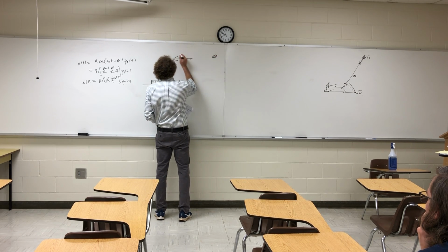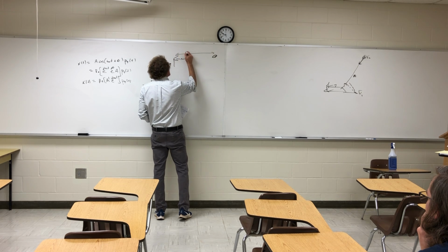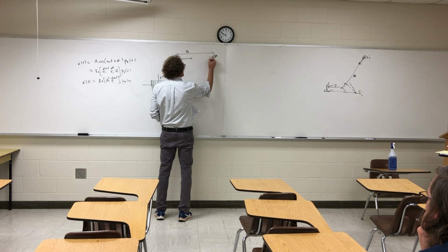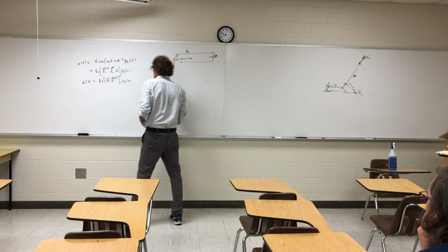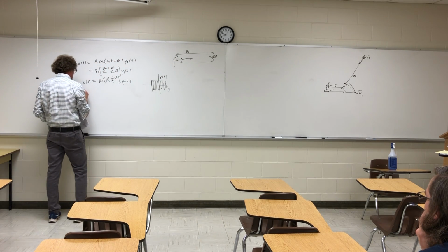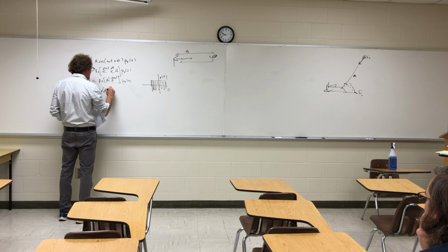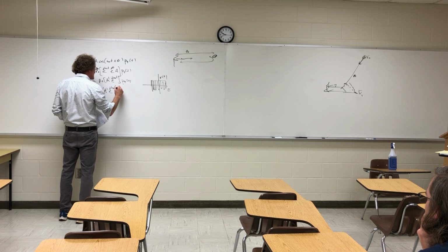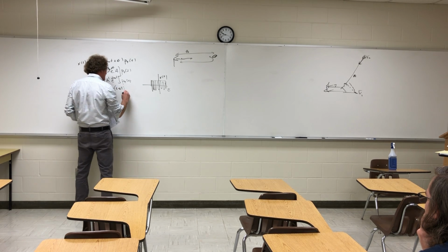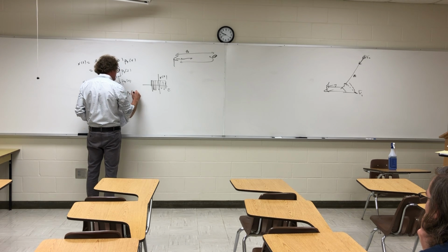It hits a target. He likes to use here the range R0, and it returns back. The return signal he calls, and I'm going to call it y of t, is equal to the real part of A prime, e to the j omega naught times (t minus delta t), p tau of (t minus delta t).